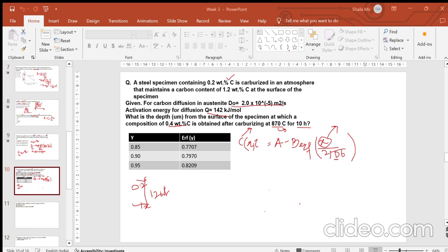70%. What are the phase fractions when the alloy is 50? So you are somewhere here, which has a 50% composition. The solidus composition is 30. So if you draw a tie line at a constant temperature, this is your 30, and then this is your liquidus line. So that is 70. Now you were at this point. This is your point. So I write it as point A.